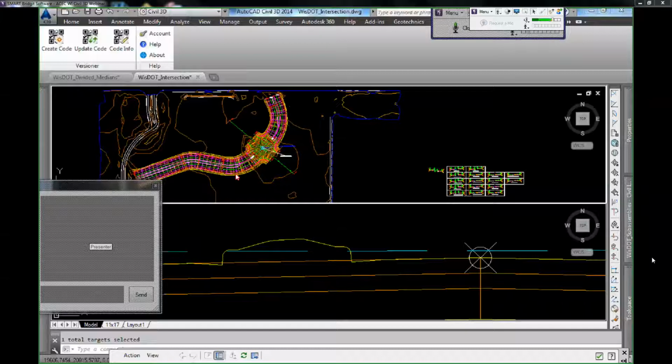So one thing that's kind of a safety, or I guess I'll call it a quality control mechanism within our workflow, is if we're not using the links to define our corridor surfaces and we are using the feature lines to define our corridor surfaces, we're much more likely to use all the correct feature lines to build that corridor surface. If we're using the links in addition to the feature lines, then there's a chance that we might forget to add a feature line, but the link is making the surface look good anyway, so that when we go to extract out our longitudinal break lines, it'd be really easy to forget one or two.